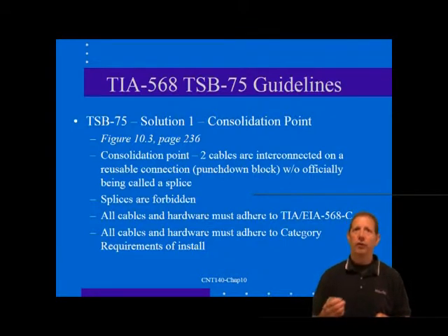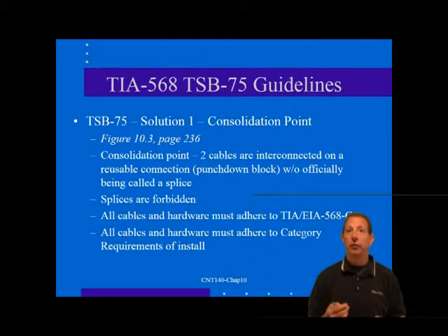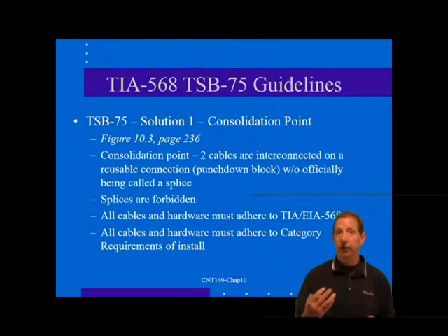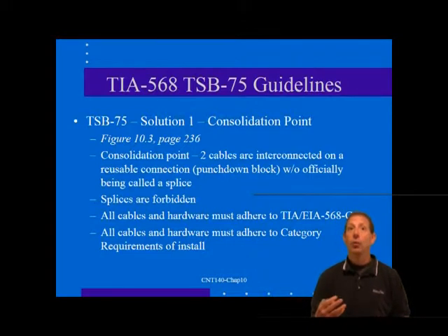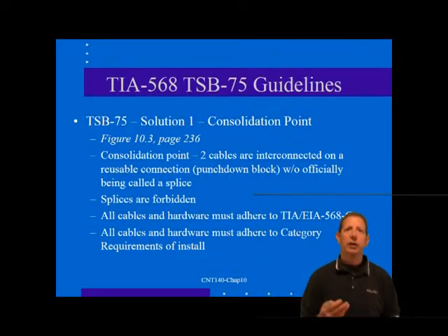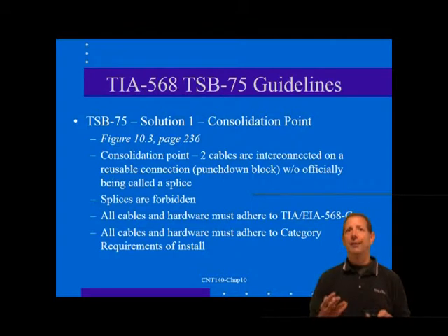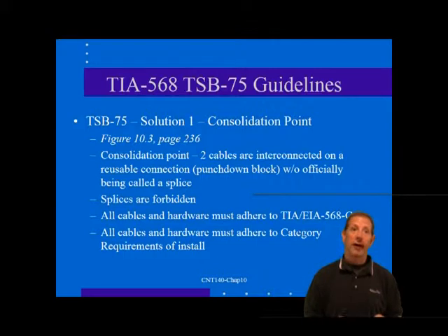The connecting hardware for the consolidation point is required to function for at least 200 mating cycles. Now, this requirement is already the case with all the normal connecting hardware under the standard, but is a more significant limit for the connecting blocks used with punch-downs. You will need to be sure that the hardware meets this limit. This number of cycles is quite sufficient in allowing for the periodic movement and reattachment of a portion of the horizontal cabling that connects to the work area outlet.